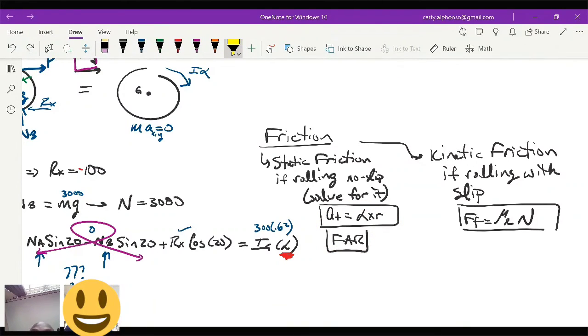But it's kinetic. It means that you're saying that it's a translational motion. It's kinetic friction. Yes. So when it's kinetic friction, it's no longer fixed axis rotation. It's general plane motion, and you can't look at it as a fixed axis rotation. That's the cool thing. When it's rolling with no slip, it's technically moving with general plane motion, but the no slip condition means that you can use the method of instant center. And because you can use the method of instant center, you can take a picture of the situation and evaluate it as if it were fixed axis rotation.